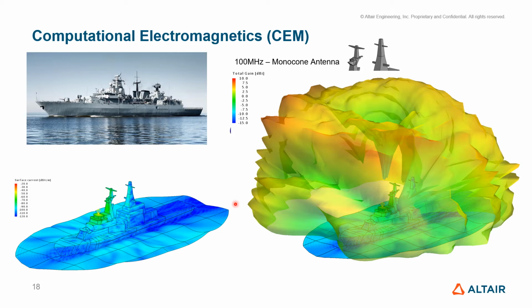The second criteria is to make sure the size of that element, when added together, can capture the current behavior. You can think of it this way, I guess. If you have one wavelength of a sinusoidal wave, how many points do you need to represent that sinusoidal wave? You can say, I can put 2 points. No, it's not going to do it. 3, 4, maybe 6, 7, maybe we're getting there. But let's say approximately 10 would reasonably represent the sinusoidal wave.